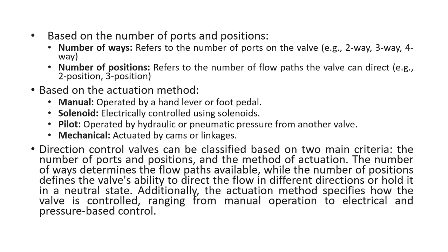Normally we use a three-way valve for a single acting cylinder. This direction control valve has three ports: one is a pressure line, one is a tank line, and one is for the forward stroke. In a single acting cylinder, the return stroke is by spring. The third one is a four-way valve, in which four ports are there: pressure line, A, B, and tank. A is for forward motion, B is for reverse motion, and T is for tank.